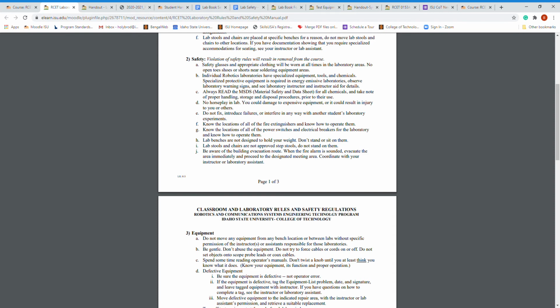Understand how to safely handle them, how to store them. If they're flammable or not. Does a spark cause a fireball? I've seen that before too. Also, one of the things you should be careful with is, if the equipment you're using is suspected to have been used with a chemical, this is kind of a good rule of thumb: make sure it's decontaminated before you start messing around with it.